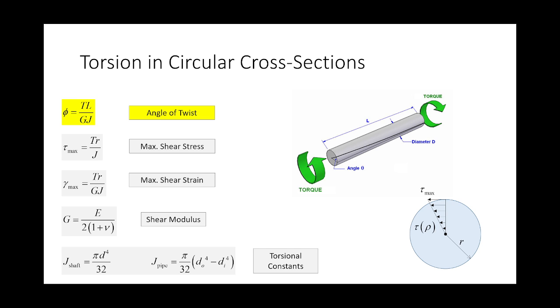So in order to determine the stress for a circular cross-section, we start to experience something that's a little new. There are some things that are a little different from axial loads, and that is that the stresses change dependent upon where you look. So for example, if you take a member and you subject it to axial force, take this eraser and just press on it, and you get 10 KSI. It's 10 KSI everywhere. It's 10 KSI here, here, here, here, here. It's a uniform stress across the board.